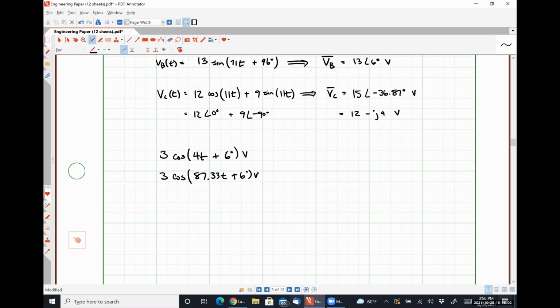Typically, on a problem like that, you start in the time domain, convert everything into the frequency domain, analyze the circuit in the frequency domain, and then use that to get back to the time domain. If you ever started in the frequency domain, the problem has to stop in the frequency domain unless you're told what omega is. That's a very fair observation. We are suppressing or completely eliminating that information. It does not get brought back in or magicked up. We have to know what omega is. Jesse.